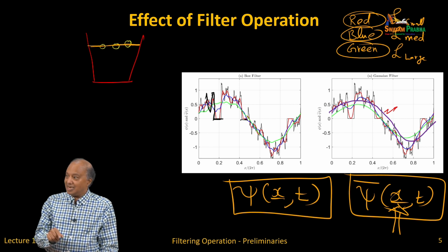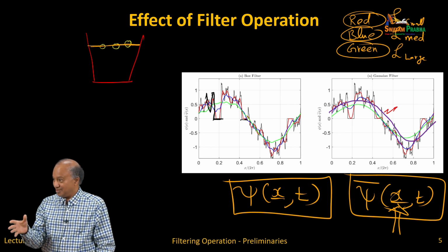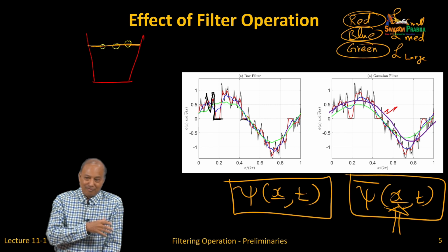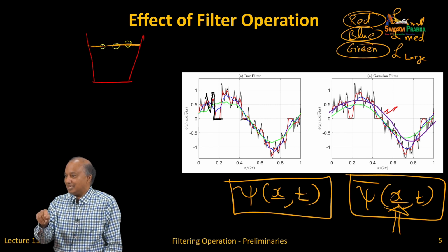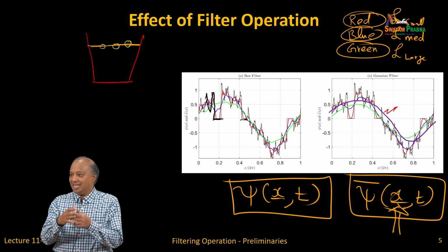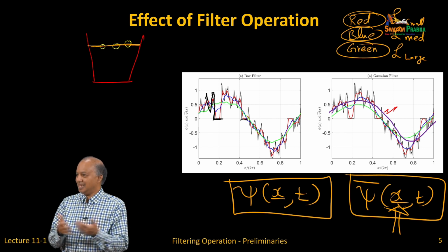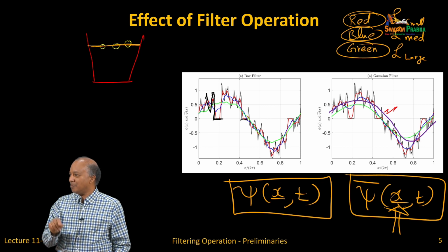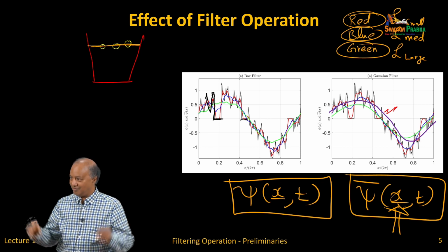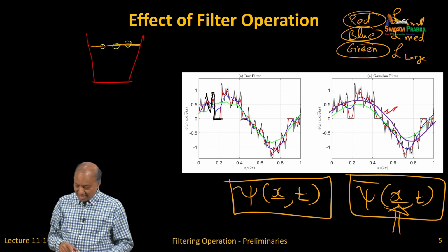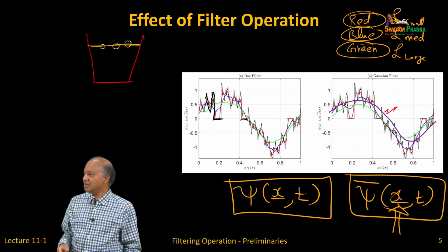Just like I said, where the particle is erased, when you do LES, you do not have to worry, am I inside the particle, outside the particle, etc. That equation is good everywhere. Same thing applies for RANS. That is why in RANS you do not have to know where the particles are, etc. You just average it. And that I just drew it as a purple line.